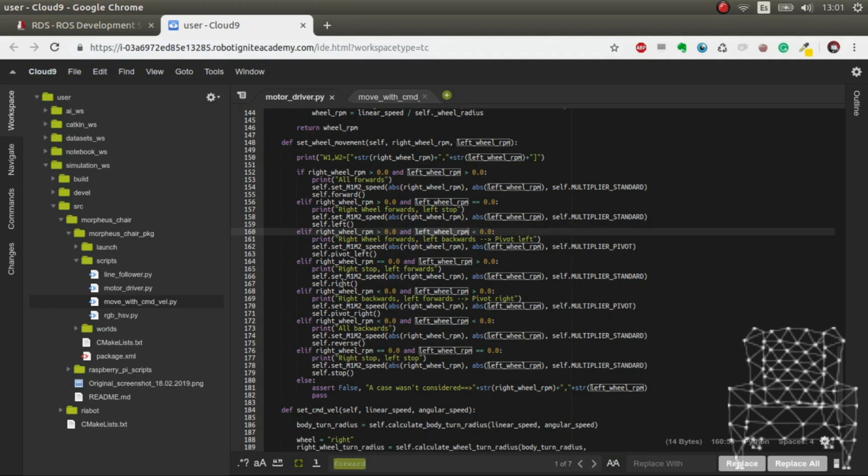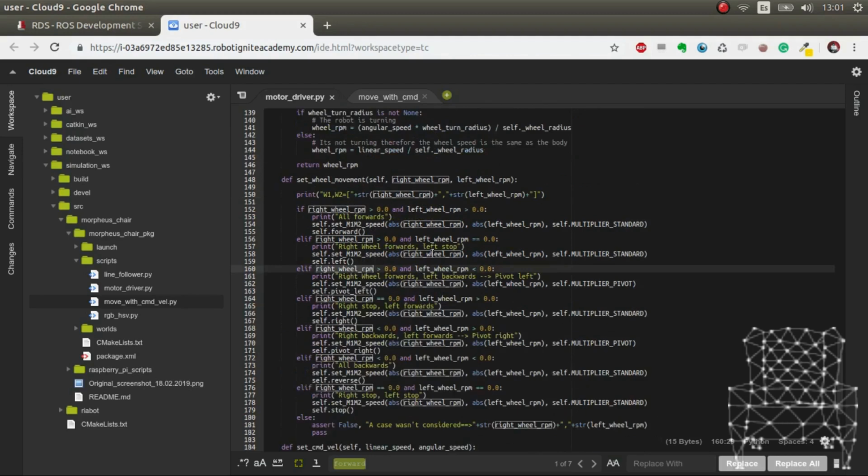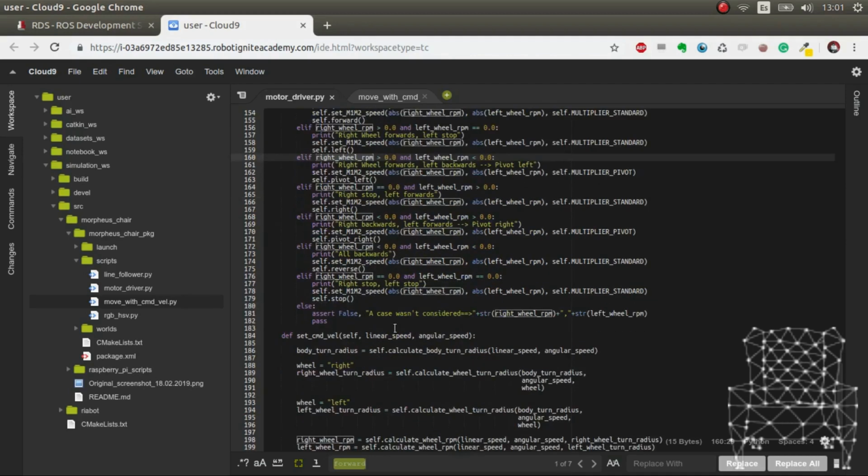And it's more or less the same thing over and over again. And the magic is done by the differential drive formulas, because that way it calculates the speed and the direction of turn of each of the wheels based on the dimensions of the robot, like the base, the wheel separation, and the wheel radius. So it's quite intelligent, actually, the differential drive.